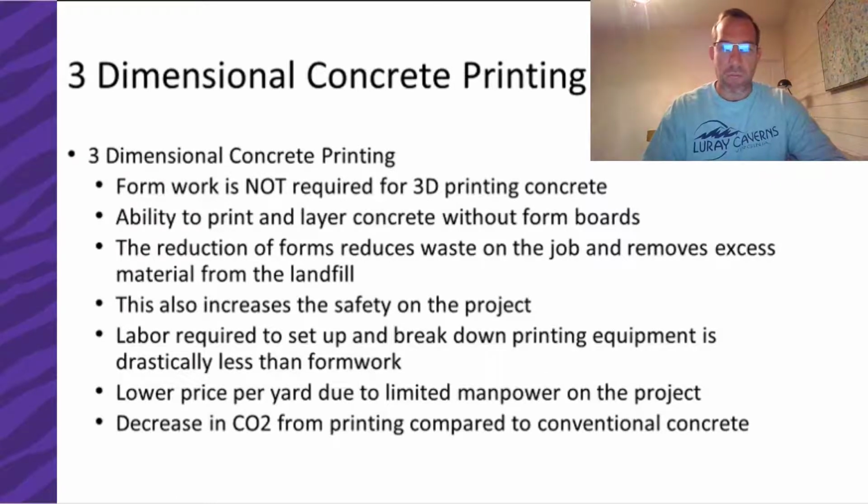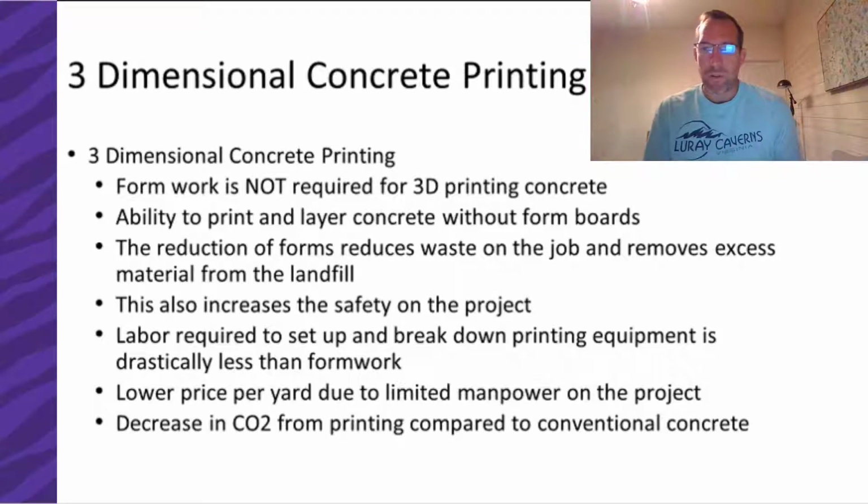Labor is required to set up and break down the printing equipment, but this is drastically less than setting up and breaking down formwork. So another added benefit. With the reduction in manpower, this is obviously going to be a lower price per yard for the concrete, which should go into your math when you're ultimately looking at a cost comparison between 3D CP and conventional concrete.